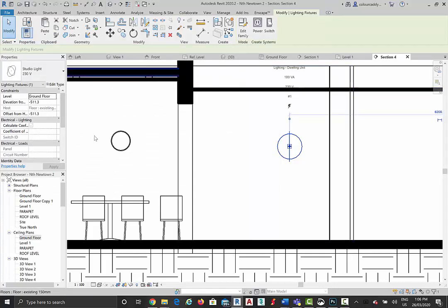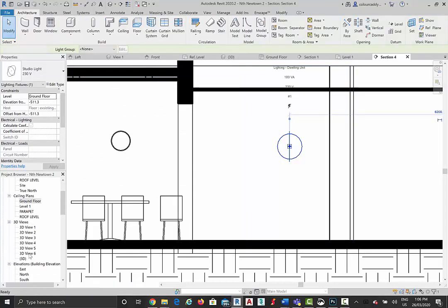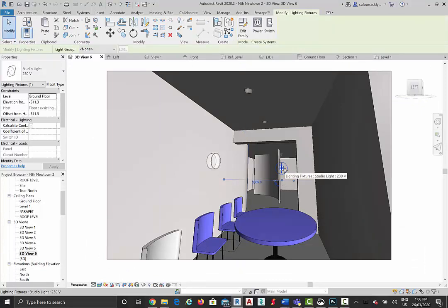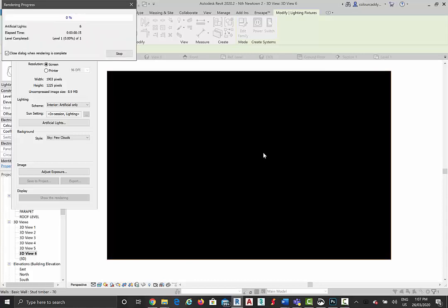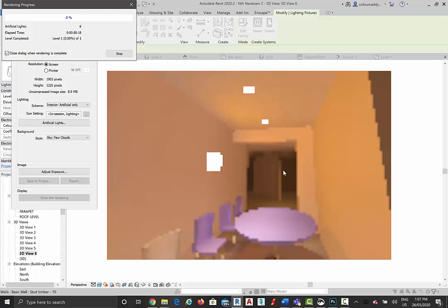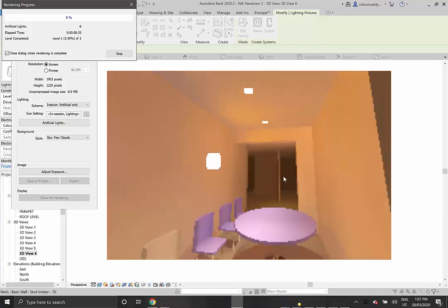So again, back to my corridor, and just quickly rendering so you can get an idea how they work. And then a great way of just filling in your space with lights when you can't get light sources, but lighting fixtures, to do what you want. It's really a cheat. You're adding these floating lights to add extra light to different spaces. So you can see now we're getting some light down there that wasn't there before. But extremely useful to be able to do that. Now, this one's still misbehaving, but I'm not going to worry about it now.